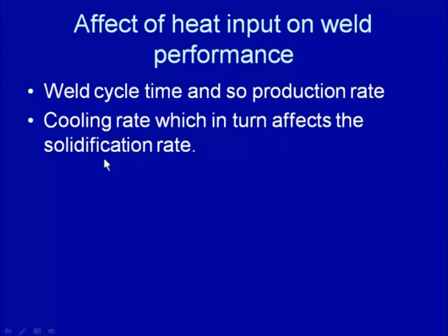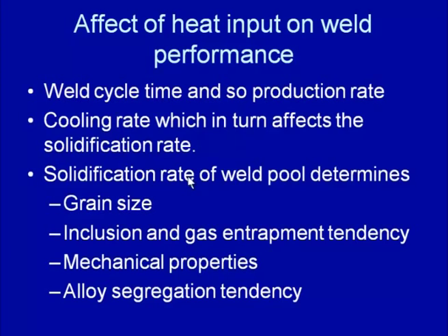So, the solidification rate will be decreasing, and the decreased solidification rate affects the soundness of the weld joint in a number of ways. Like say the solidification rate of the weld pool determines the grain size, the inclusions and the gas entrapment tendency, the mechanical properties, and the alloy segregation.